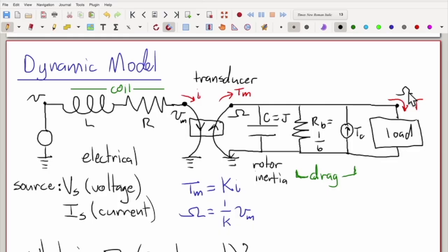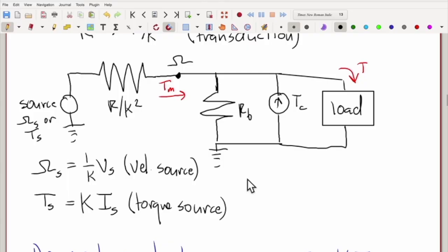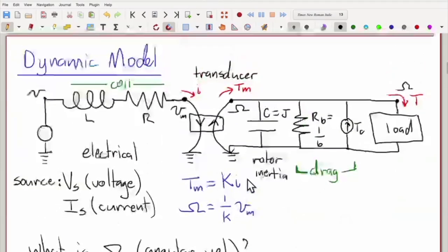And from that, you would generate a frequency domain transfer function that you would use to design your PID controller, for example. So that's the other way you could use this: you use this full model, or maybe this reduced steady state model if your dynamics are slow relative to your inertia, to derive a transfer function. Okay, and that concludes the video.